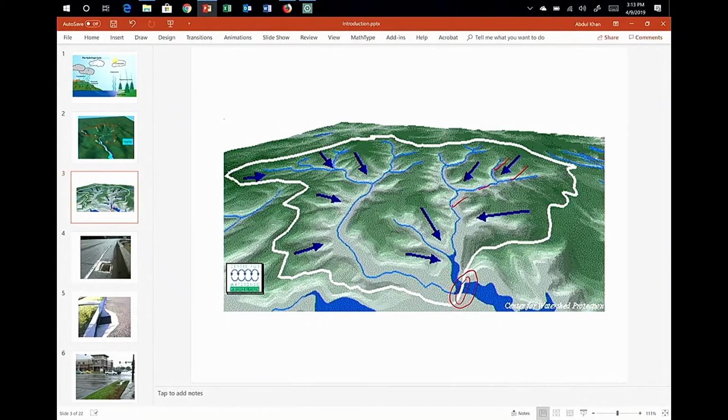So you can basically go to any software, for example GIS, and click on a river, and it will give you the watershed of that point. So you can draw a watershed at a different point in the river. For example, I can draw a watershed for this point, and that will look something, let's say, like this. So that will be a sub-watershed of this watershed.